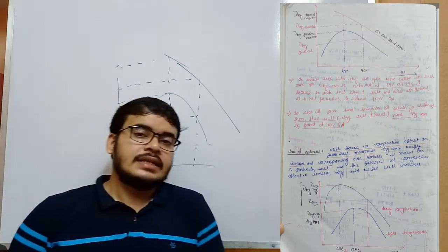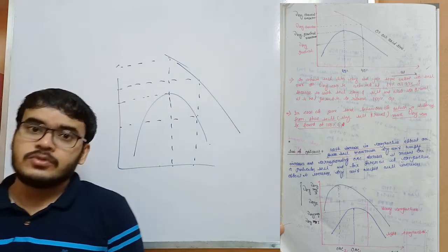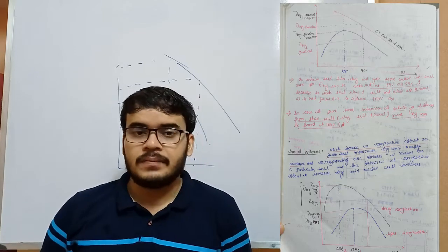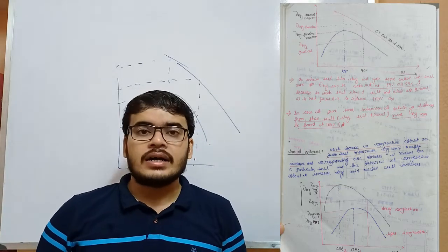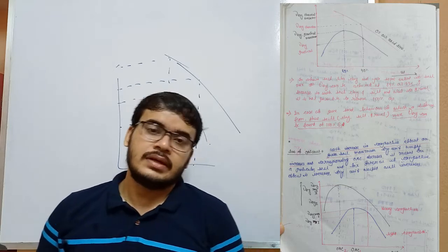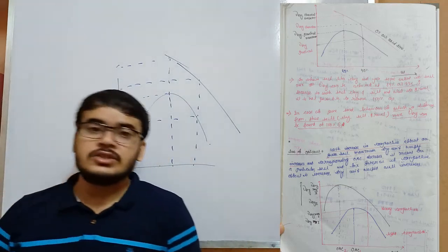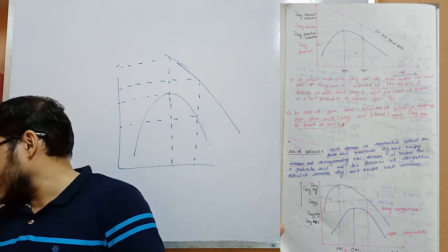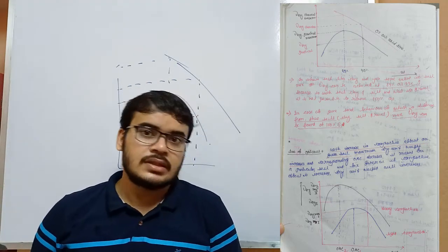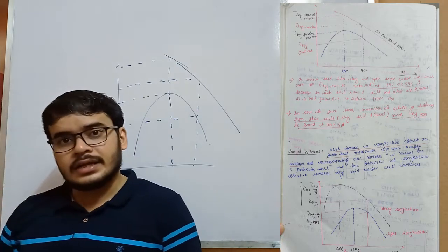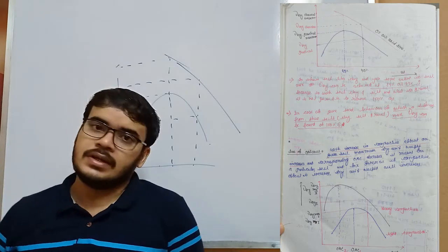That means in sand we can remove all the air, but in clay and silt, as the voids are very small, we can't remove the whole amount of air. That's why we can assume that at 85% to 95% degree of saturation we get the maximum gamma dry value.